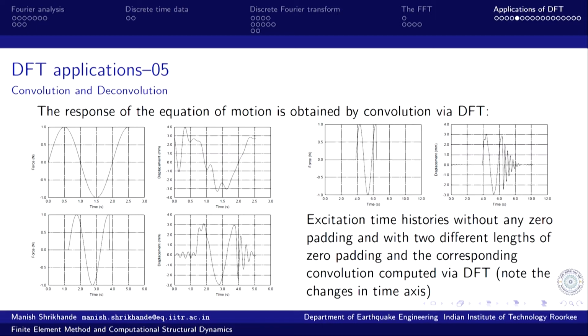Once we do that, we see the ripples are reduced almost to a negligible extent, and particularly at the beginning of the true excitation it is almost imperceptible. The solution starts from at rest condition, and at the time of withdrawal of the excitation the free vibration response follows as it should, correctly.